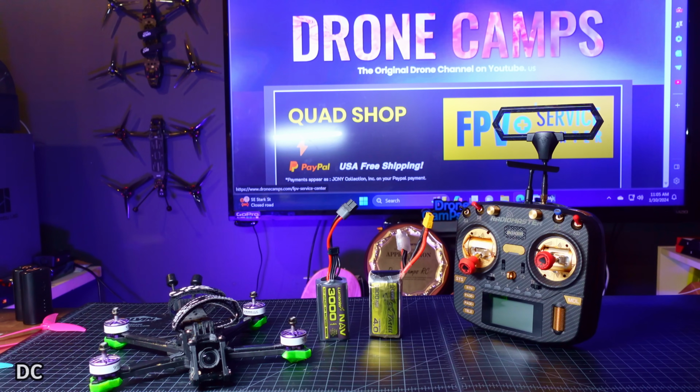Now, you have to test that on the drone that you're flying to see if the Li-ion is actually going to work on your quad. I've had similar power systems where I thought, well, this quad works on a Li-ion, so this quad should work on a Li-ion. And then when I tried the Li-ion on the other quad, it didn't really work out. And you'll know because the quad won't really take off and fly very far.